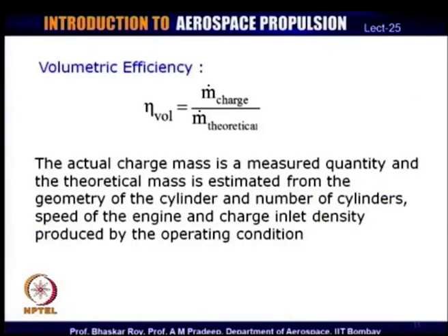Otherwise, the volumetric efficiency as it is defined now would come into the picture, and it is simply defined as the charge that is coming in or the charge that is now available divided by the theoretical charge which we assume to be effective in the cylinder. So, the ratio of the two is the volumetric efficiency.